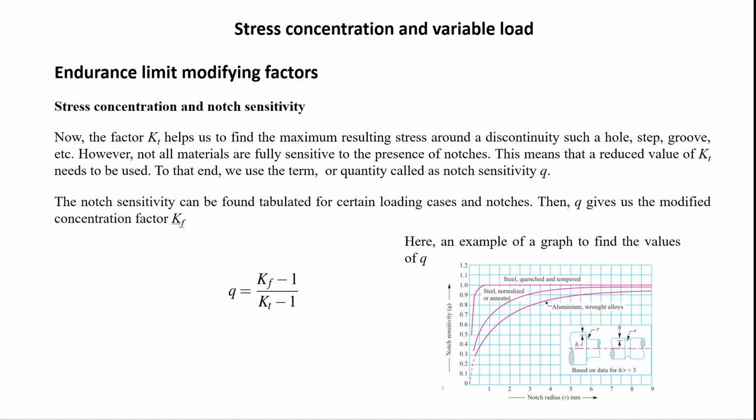And that comes to what I mentioned. Stress concentration is also used in fatigue design via a parameter called notch sensitivity. Finding out the notch sensitivity, which is a formula that we could use or calculate according to certain charts, is going to give me a factor of Kf. Now, this is a very big distinction I want to point out right now.